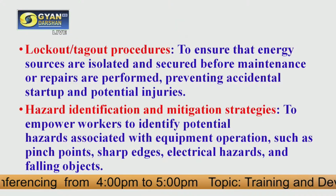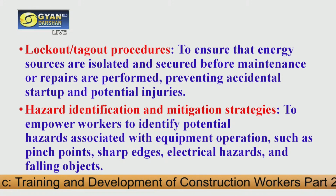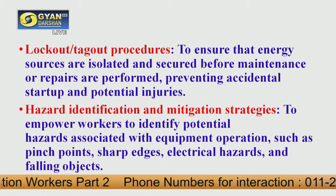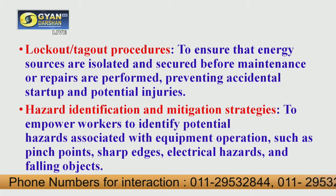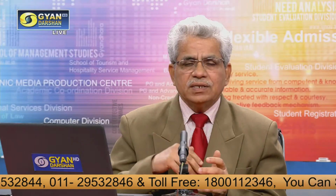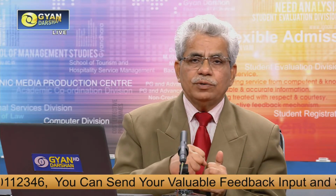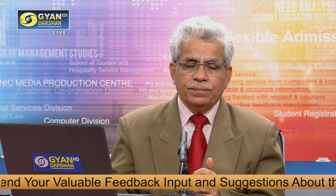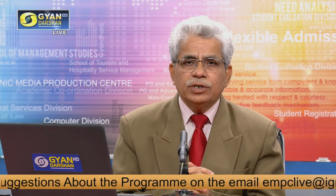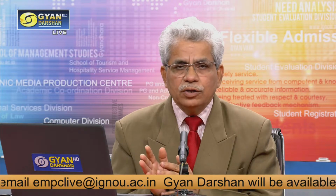Then the lockout tagout procedure. What is that? If you are intending that this tool will not be used, then there should be proper lockout and tagout, so that one does not accidentally use that equipment. We say that these accidents occur because of energy transfer, the transfer of energy from a tool, equipment or machinery to the human body. So by doing this lockout and tagout procedure, we are ensuring that there is no chance of transfer of energy from equipment to the human being.